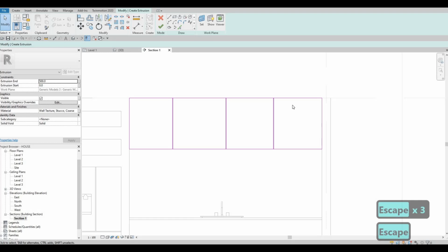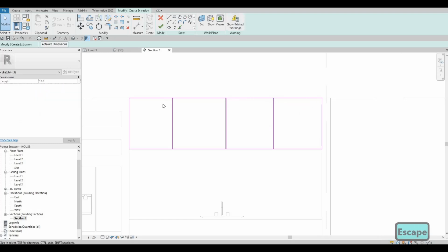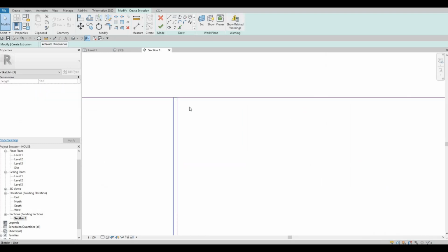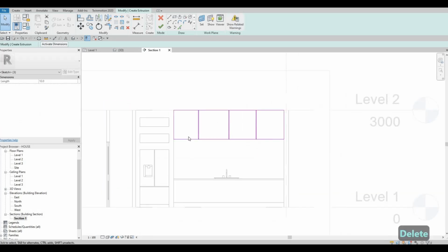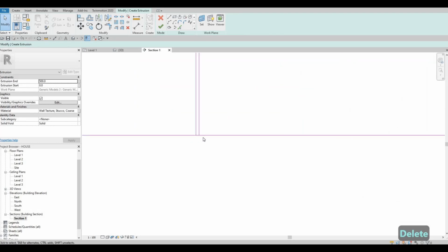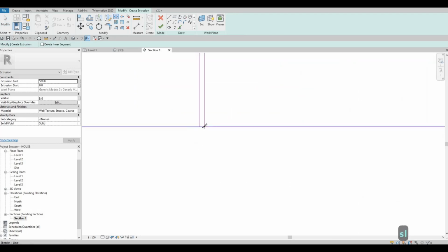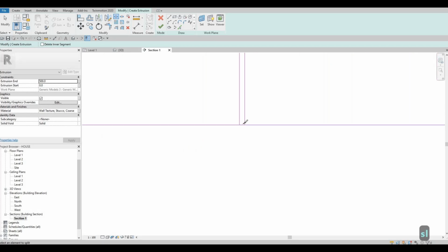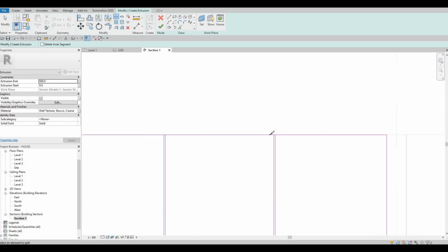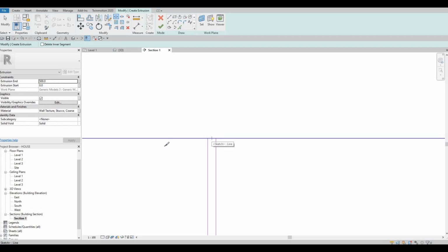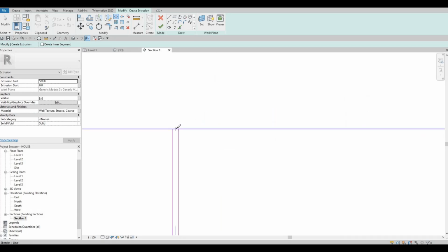After that, we created some multiple lines, so I'm going to do that so that we could delete those ones that are small, and this one as well at the bottom. After that, we need to use SL, split element, here as well, and then here as well. At the top, and then now after we finish that, press escape, TR, trim extend.